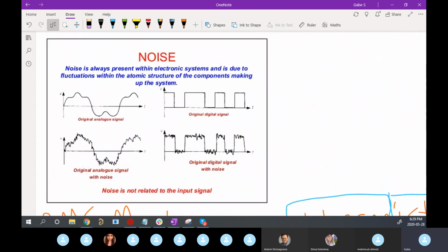So the noise that the signal is going to pick up is the same whether you're a digital signal or an analog signal. That noise in the environment exists no matter what, and it's going to pick it up in both cases. But the problem with the analog signal case is that all of these values are valid, right? So let's say we're just looking at positive, for example. All of these values between 0 and 5 volts are absolutely valid for the ADC to be measuring, or for the analog signal to be at. And so if you get noise, it's really hard to tell what was noise and what was your actual real signal. Because if my signal was at 4.2 volts and it had some noise and spiked up to 4.4, that could totally be a reasonable value.